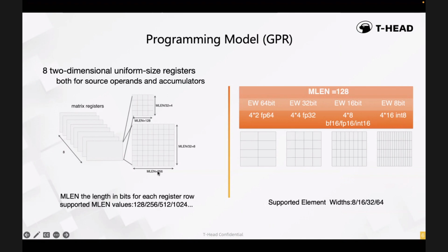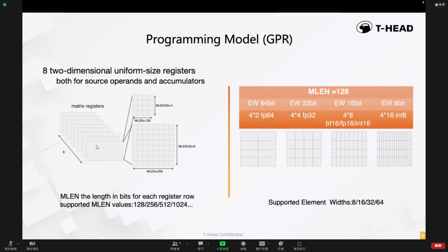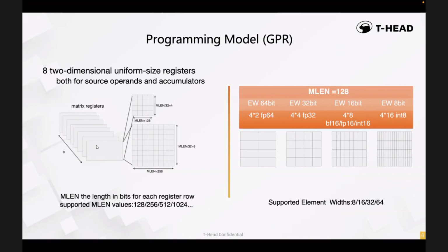Okay, thank you. I have a question regarding how the instruction works. You now have matrices which have different dimensions, right? So can I treat any matrix register as both A and B, and do they get transposed? Because now you have an asymmetry in the dimensions of the matrices. So how does the matrix operation work on these registers, and how does it accumulate into the final registers? Because the dimensions need to come together in the matrix multiply itself.